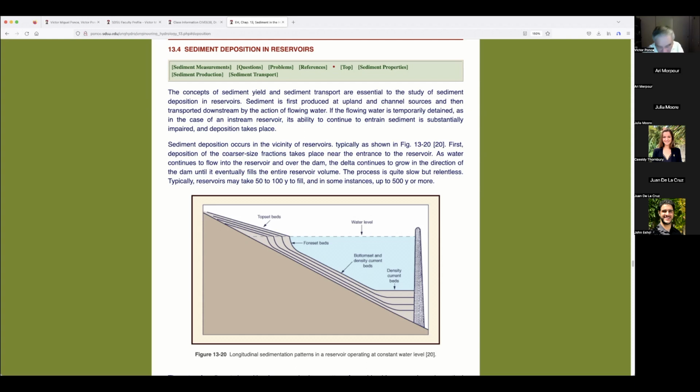for the simple reason that the chaparral survives by virtue of protecting itself against exaggerated evapotranspiration by covering itself with wax, naturally speaking. And then when they cover themselves with wax, when it burns after a fire or during and after a fire, the wax dissolves and it hits the ground and it stays there, and it creates a non-wettable layer of soil. And that's what leads to the debris flows.